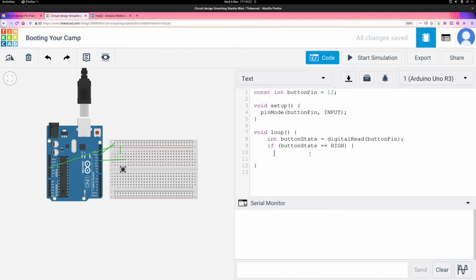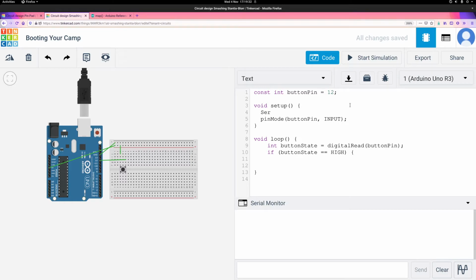And combine things. And I can have that as a quiz to reinforce what everyone picked up from the last examples. So first of all, we'll try the serial output. So we'll remember what we need for that. We need to set it up. So we'll do serial begin, give it a baud rate. We'll use our default of 9600. Then if our button is pressed, is essentially what this is saying.